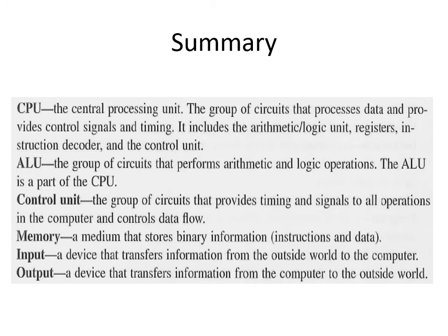Now you can summarize the microprocessor based system. It consists of a CPU, a central processing unit. It includes the ALU, the registers, the instruction decoder, and the control unit. The purpose of the instruction decoder is that when you fetch an instruction, the instruction is brought to the instruction register, and from the instruction register, using the instruction decoder, you decode the instruction and identify what the instruction is and what its purpose is, and the ALU will perform the required operation.